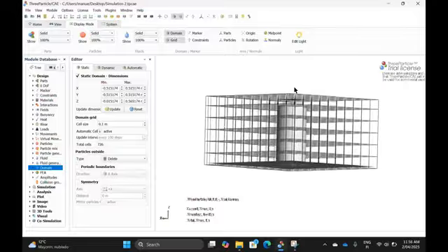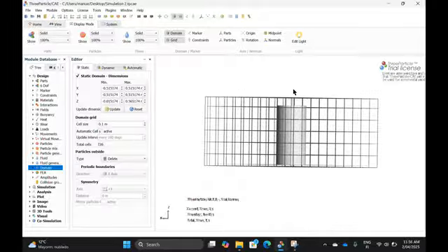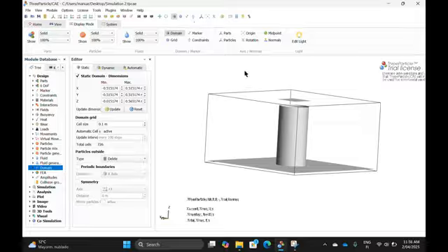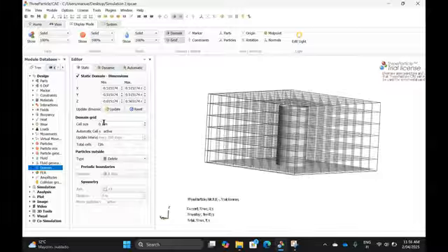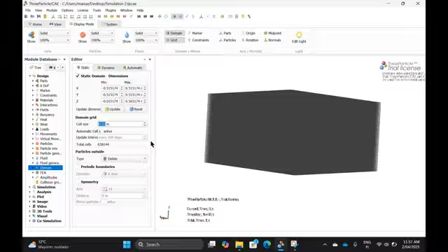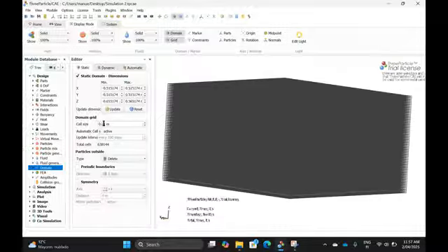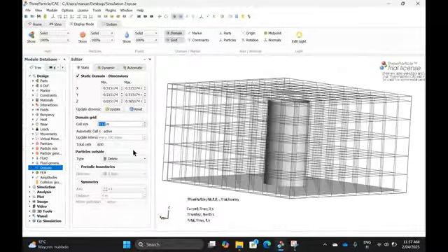If you have a very small cell size, for example like that, much more cells, more to compute. If it's bigger, something like that, it's okay. Not that many cells, about 1,000. That's okay, but the computation of the contacts might be a little bit more complex. So there is a trade-off in either direction.